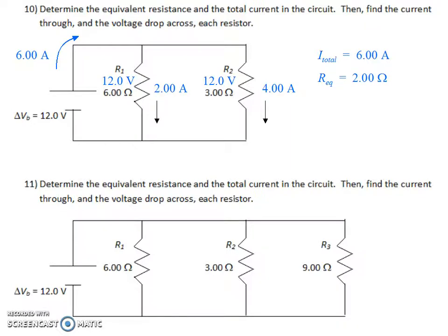And we're back. So hopefully, first of all, you should have noticed that all 3 of these are in parallel. And we know that parallel connections are independent of each other, which means putting R3 here actually shouldn't affect anything about R1 and R2, which means they do the exact same thing they did before. Since these are the exact same resistors connected to the same battery, there's literally nothing different about what the 6 ohm resistor and the 3 ohm resistor do in this circuit compared to this circuit, at least ideally.